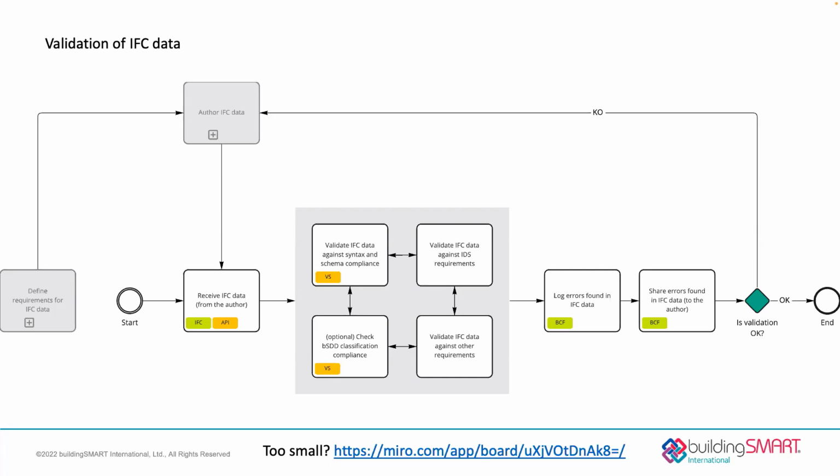But MVDs, as in: I have this use case, and I completely refined what I need. I even tweaked IFC for it, and I changed how you should do the date time format and how you should do the geometry. And I want that checked. No, we're not going to do that anymore because we don't want to allow tweaking and fine-tuning of IFC anymore.